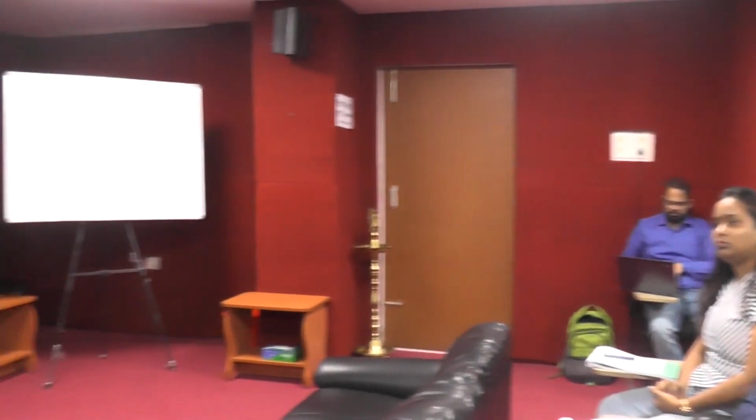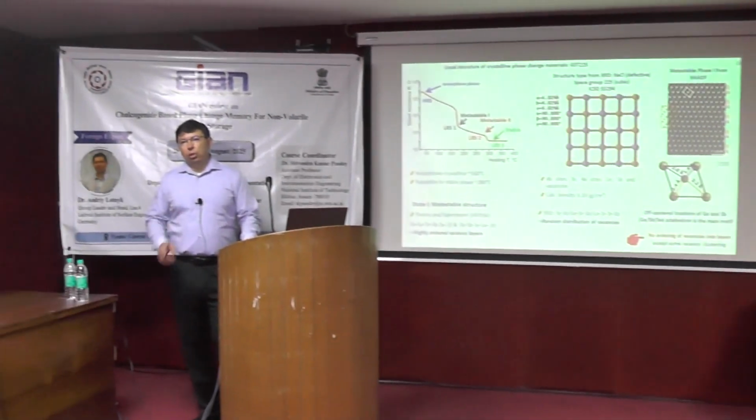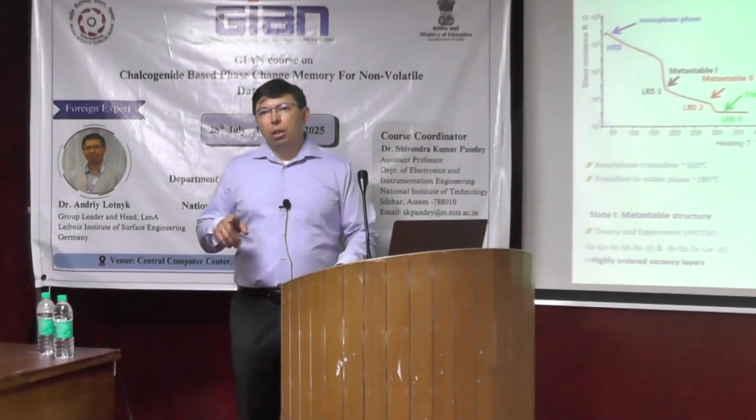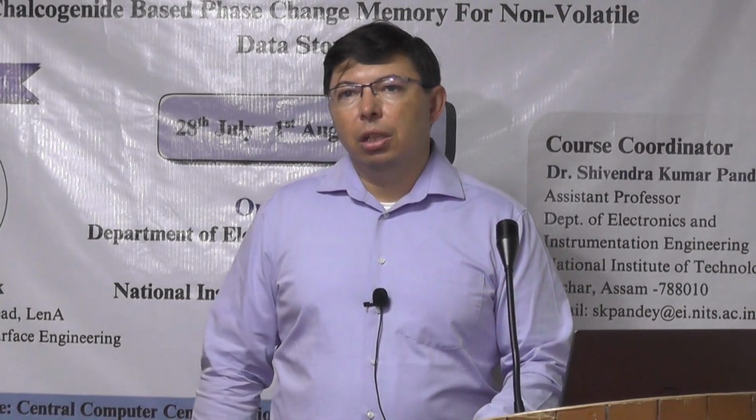I think it's dependent on both temperature and composition. My idea was to study it at different temperatures to see if the peaks are disappearing. I think maybe it was not a full crystallization. So if you still have the presence of some peaks from the amorphous phase, it's a signature that you have both phases in the material.